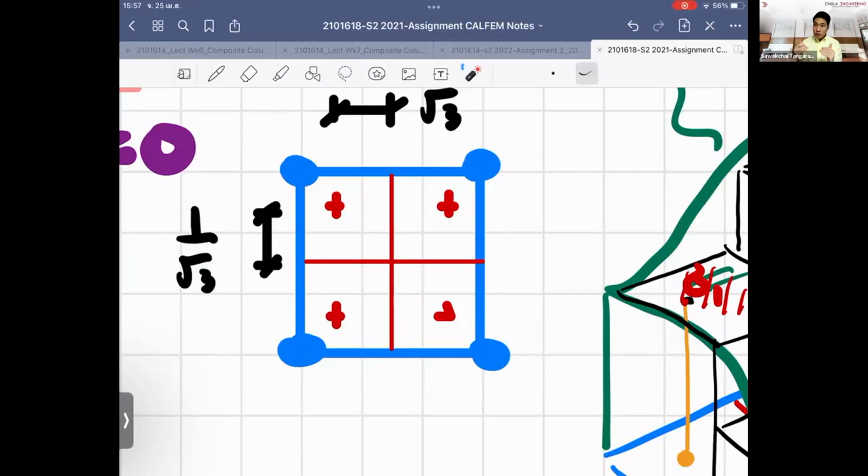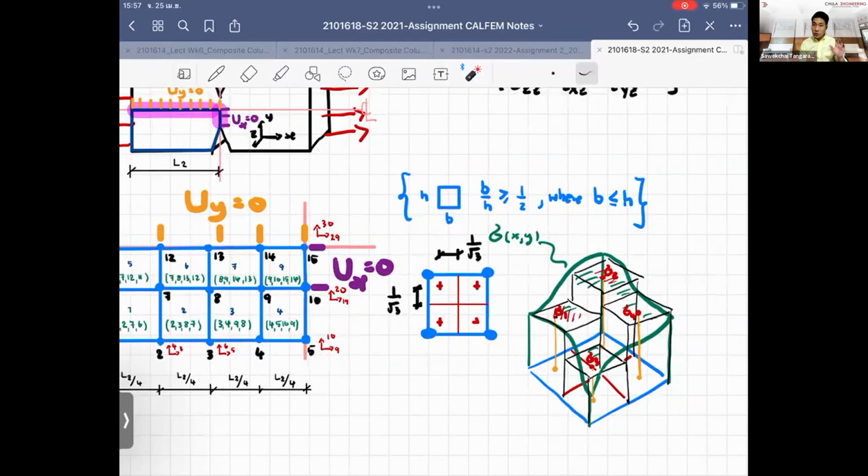There is a rule, theoretically proved, for how many Gauss points work for what order of function you assume in the displacement field, right? The more you increase the order of the displacement field, meaning rather than a linear shape function you use a nonlinear shape function, the more accuracy you have, but of course it will take more computing effort.